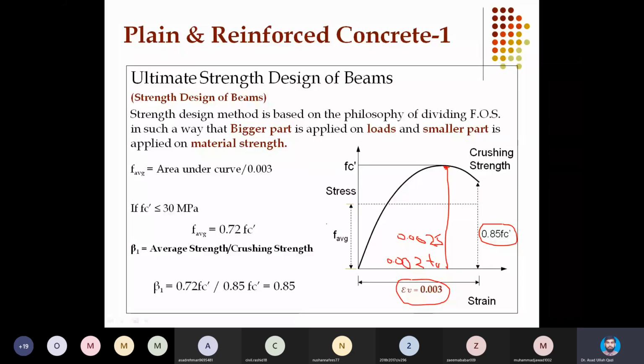If the stress strain relationship is linear, we will get a triangular area, as you have seen for homogeneous elastic beams or the concrete in the very initial range subjected to very low levels of stress. But in ultimate strain design, since we will load the specimen cross sections to their maximum limit, to their crushing stage, we will get a nonlinear stress strain range, and so we need to determine the area under that parabolic curve.